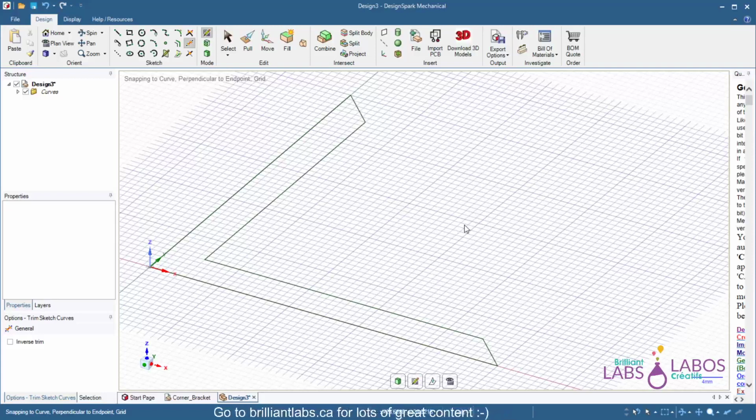And we're going to get ready to actually create the 3D of this, which is actually a pull feature in this particular program. Other programs might call it an extrusion. This one calls it a pull. So what we can do, for the first time now, is go to the pull menu. And we're going to use this a number of times today.